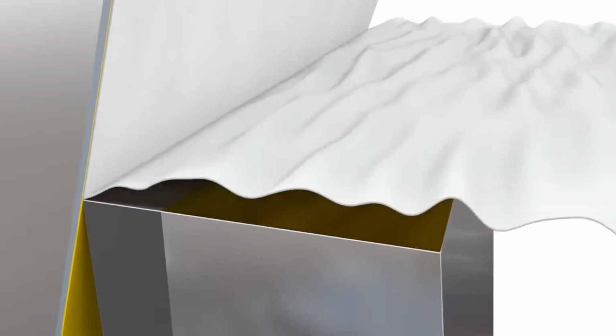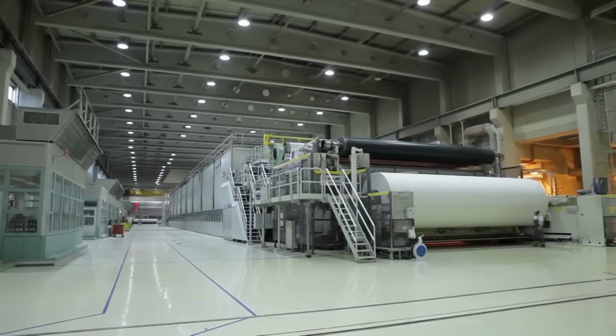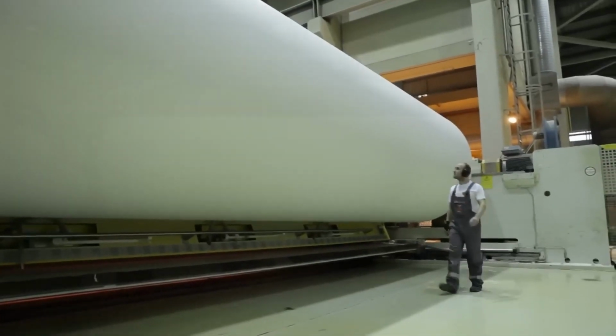The finished paper is then wrapped around a drying cylinder called a Yankee dryer and then creped, a treatment that makes it extremely soft and gives it a slightly curled appearance. During creping, the paper is scraped from the dryer cylinder with a metal blade, making the sheets flexible but reducing their strength and thickness so that they easily disintegrate when wet.